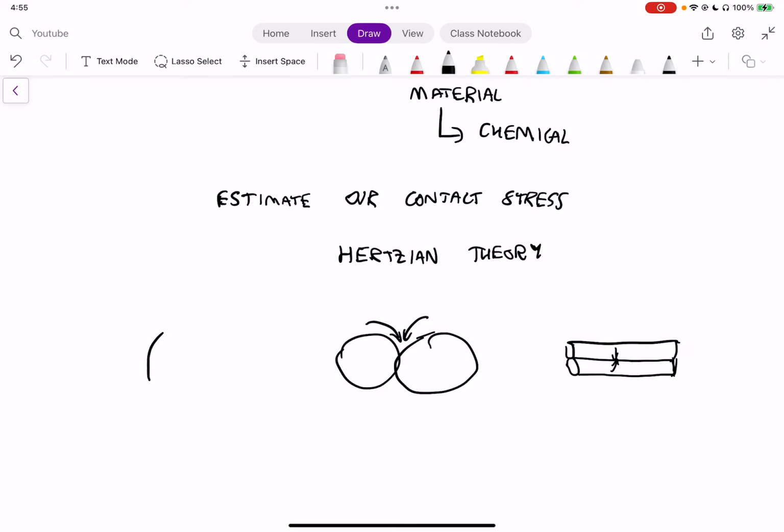Now, if we think of the motion of our gear teeth, they are doing this rolling motion through the whole surface. If I highlight the surface, essentially we have a rolling motion happening on the surface of the tooth. So one way in which we can solve for durability is from a surface durability standpoint, from a Hertzian theory standpoint, where we have two cylinders rolling on each other, which would mimic how gear teeth work when in contact with each other, because they're essentially rolling on each other due to the involute shape that they have.